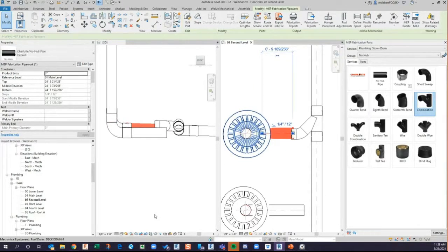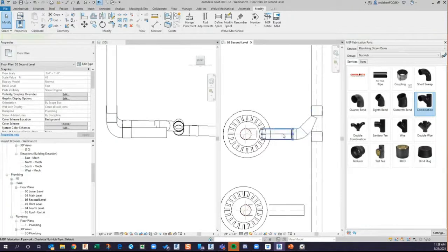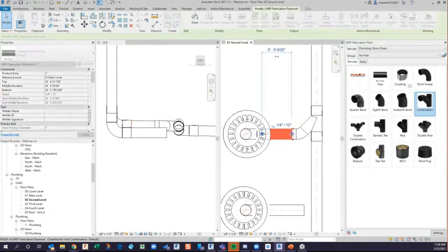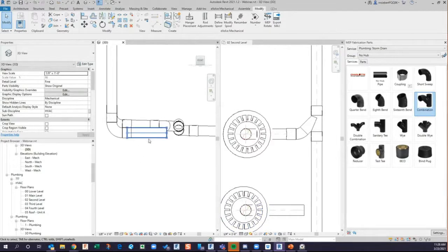So note, and this is one of the things I do like about Revit that you can't do in AutoCAD. Right there, I just select that pipe, and I'm just going to bring it on up. Make sure that I've got it at the right elevation. Now I can make sure that I'm going to connect this pipe. I'm just going to snap it to that, hold my shift key, make sure it's connected, release. It's all connected up, got that line done, and I'm going to do this one real quick as well.